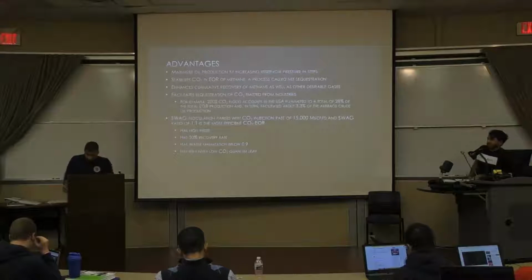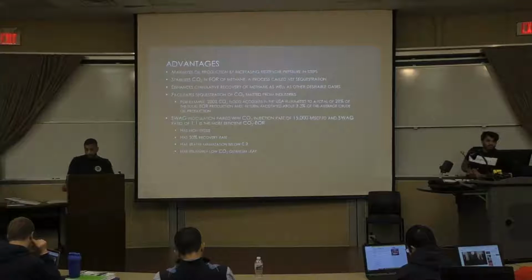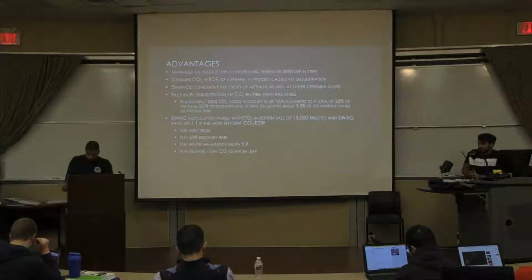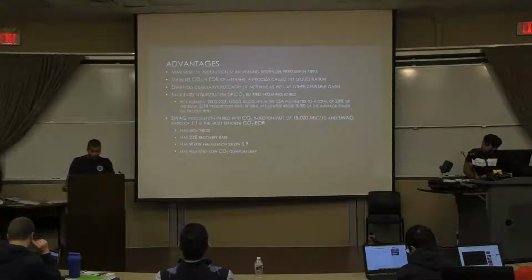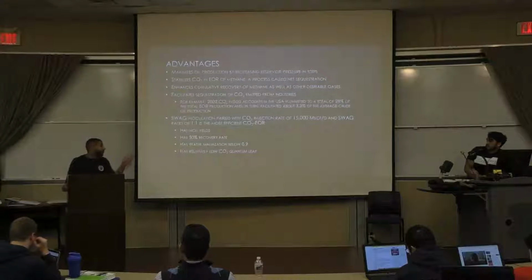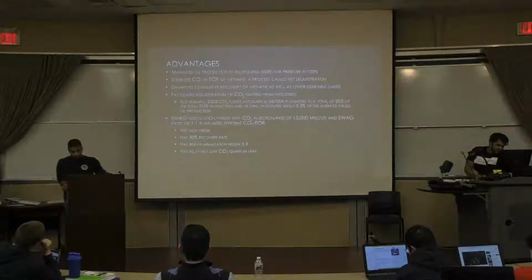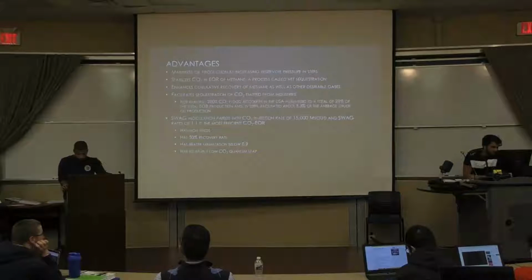Of the various forms of carbon injection method, SWAG injection paired with a carbon dioxide injection rate of 15,000 and a SWAG ratio of 1:1 is the most efficient one because it has a high recovery factor of 50%, a water cut below 0.9 and a relatively low carbon dioxide breakthrough.